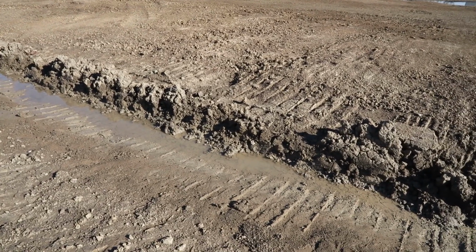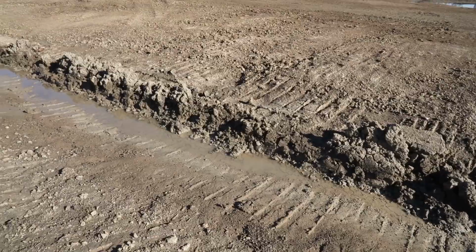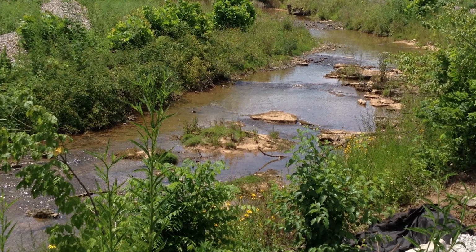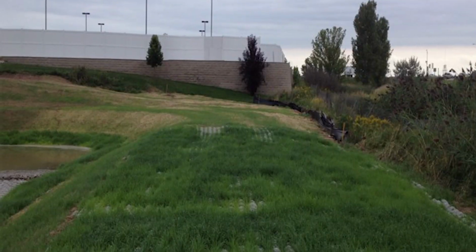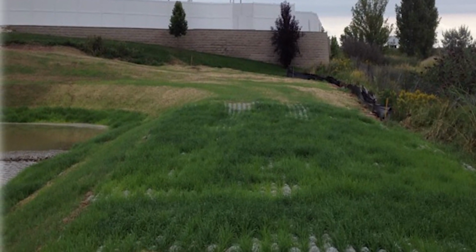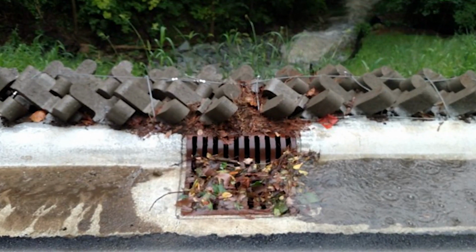Make sure the progression of the work on the site does not interfere with the emergency routing plan. If construction is going to start in the area where your run-on or run-off BMPs are located, then these practices need to be moved and the stormwater flow redirected prior to the start of the construction in the area. Otherwise, your BMPs will not function properly.